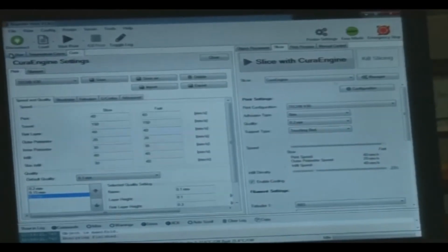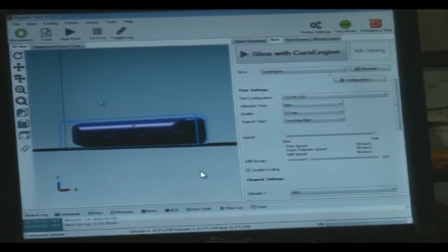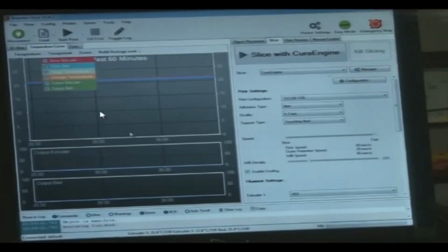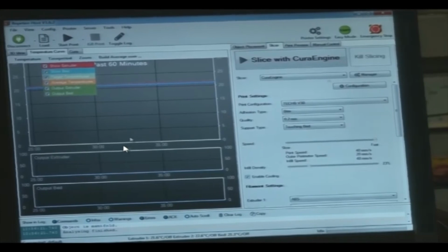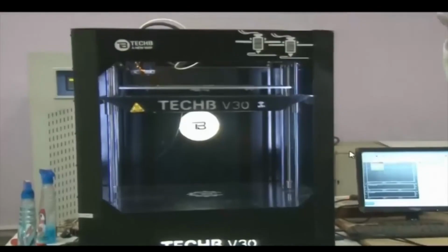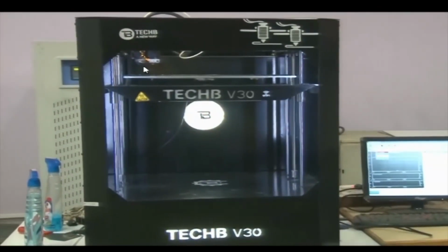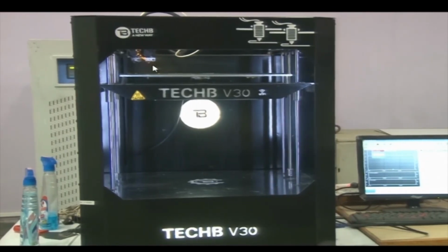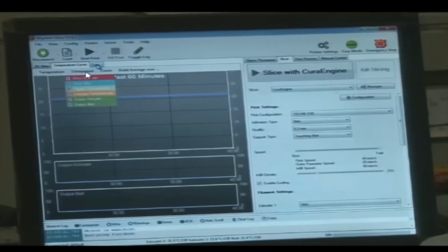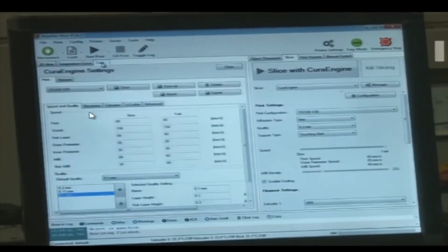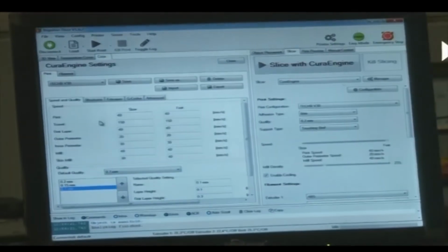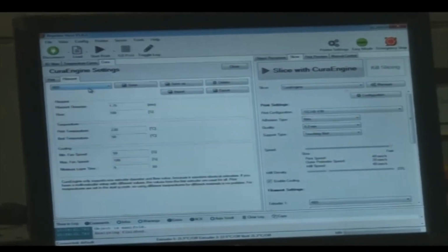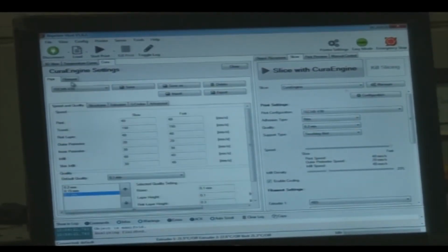This is the 3D view in Cura, with the temperature curve. The temperature curve we can see when we actually do machining. At the nozzle, heaters are there, and the heaters are supposed to heat to fuse the raw material. From the orifice the material would come, and this temperature would be shown in the window. So in Cura we have these settings. We can talk about print or filament here.